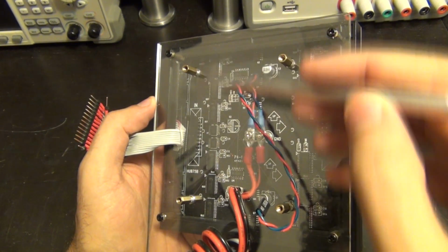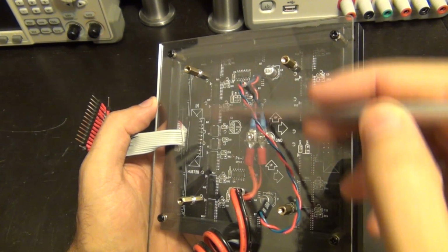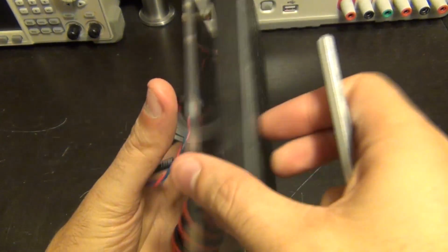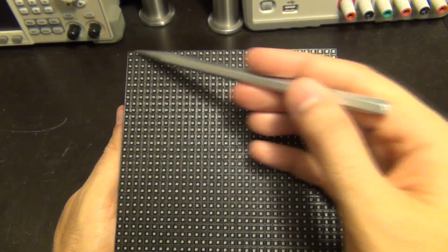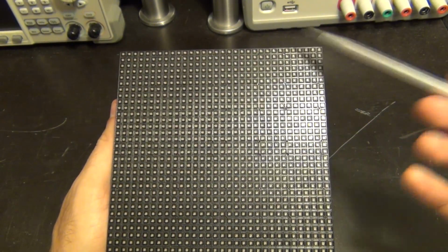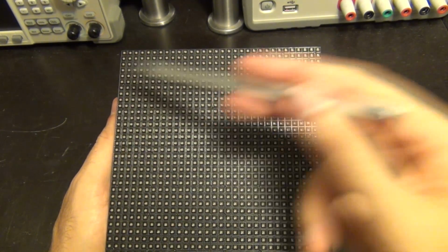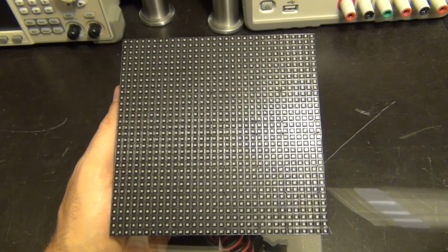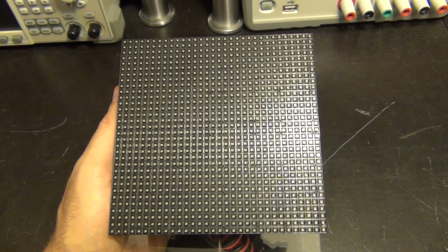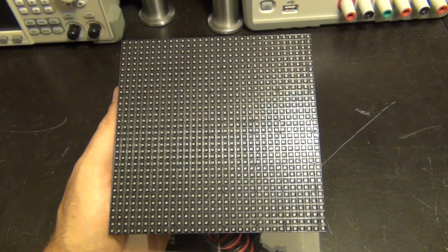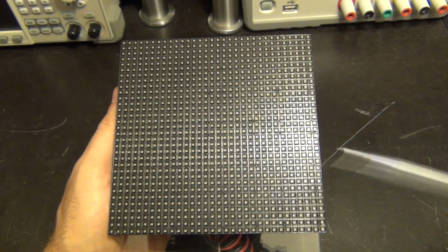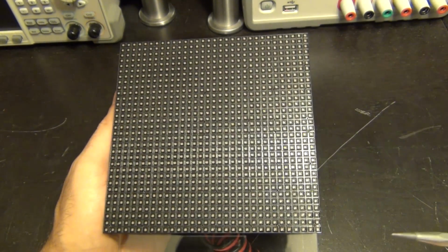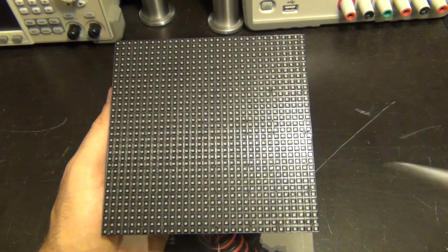And so each individual IC driver that you see under the main big ICs on this side and this side are the ICs that drive each individual row of LEDs here. So there's 32 LEDs in there. That means that each of them is in red, green, and blue. So you're going to have that 3 times 32 constant current drivers. Now they use constant current drivers for LEDs for obvious reasons, to make sure that the current through the LED is the same regardless of power supply variation between different panels, and that keeps the same brightness and therefore the same color. And that's really important. This is very common, of course. I'm sure you know about that.